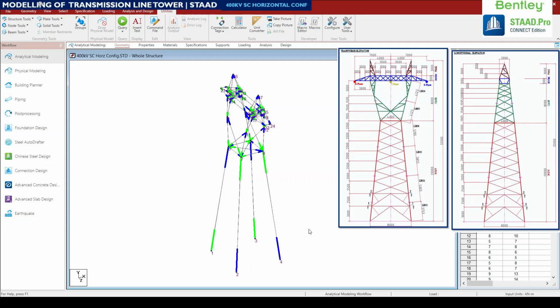To view the member numbers we press Shift B on the keyboard, so that members 2 and 4 can be changed for their starting and end points. For our visual purpose we can delete these pictures.